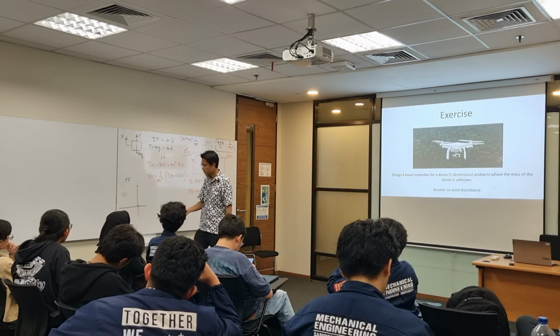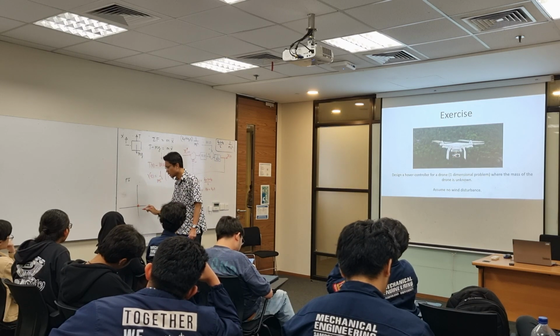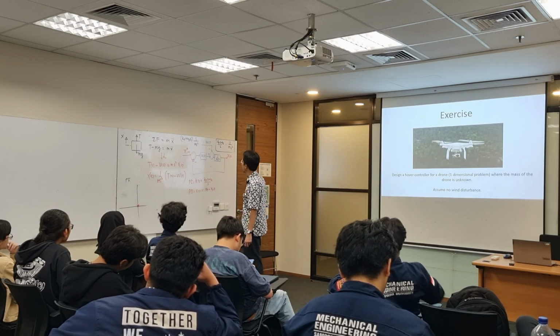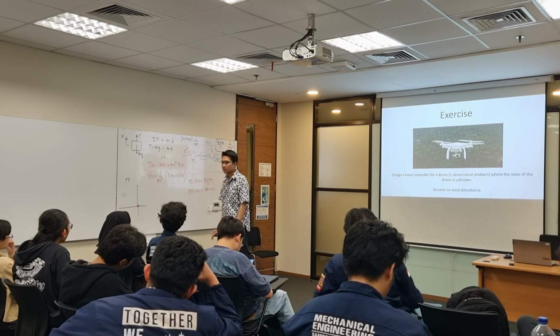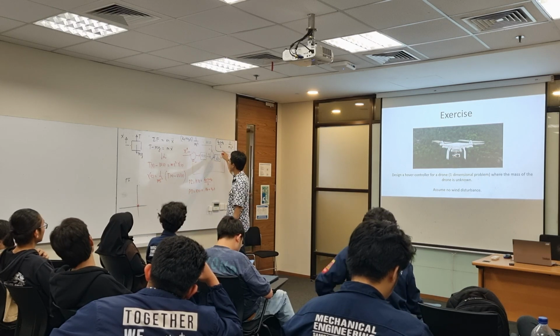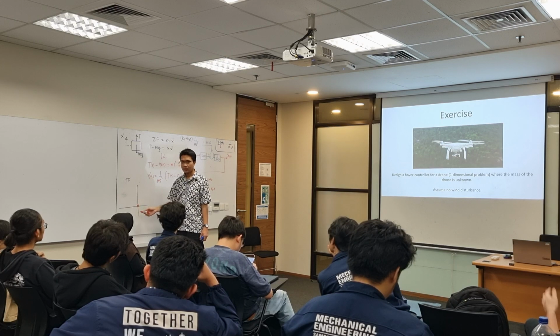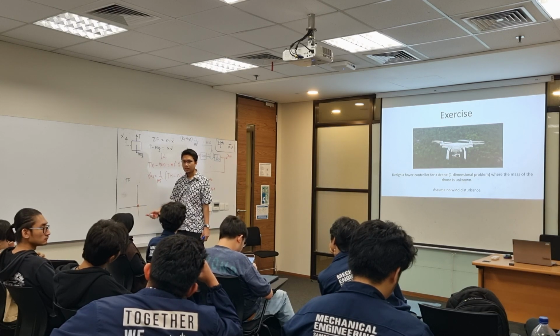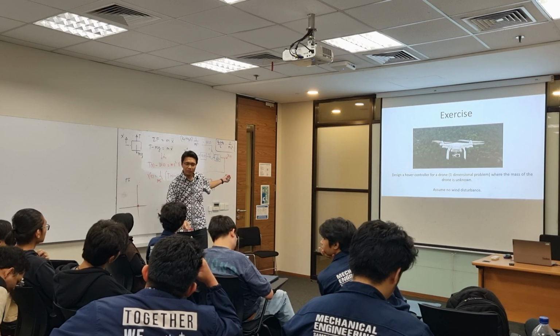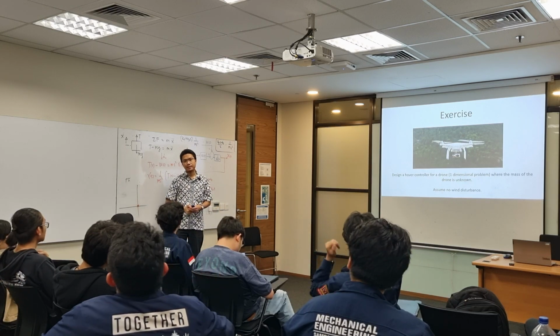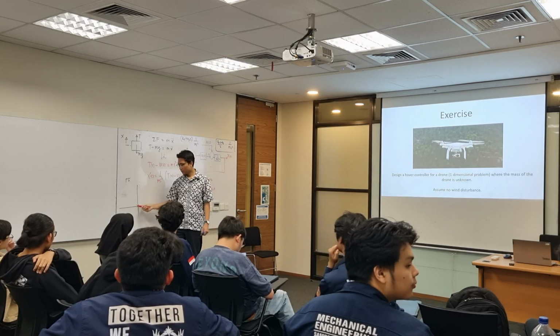I'm talking about the root locus. So the open loop poles are all here. How many poles do you count? What's the power of S in there? 3. So we have 3 open loop poles, and all of them are at the origin.